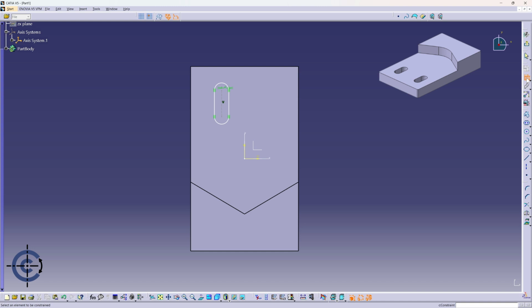Now we go to the dimension tool. I'm going to offset this from the main axis by 12. I'm going to change the length of it to 10. And you'll notice there isn't a center point here to set the distance if I wanted to choose the center.